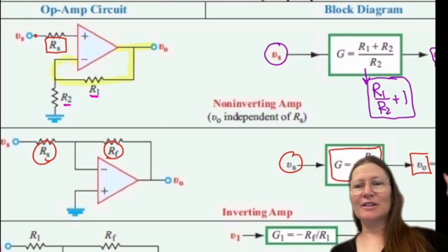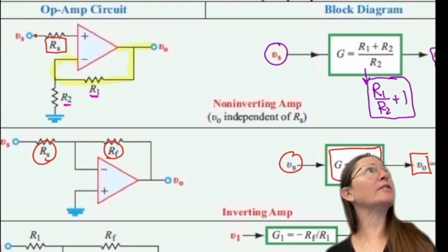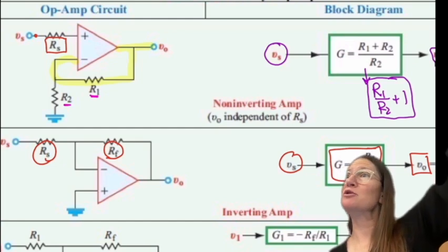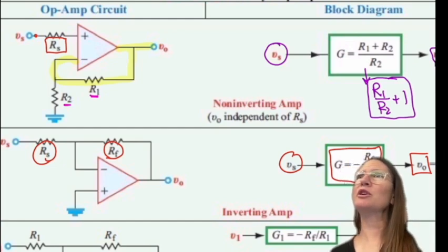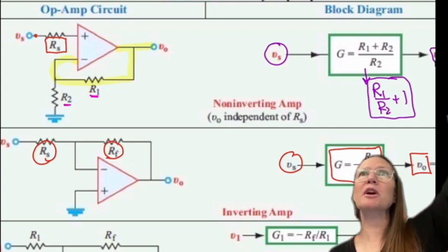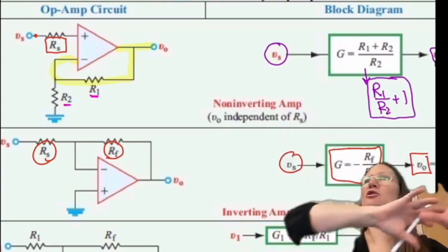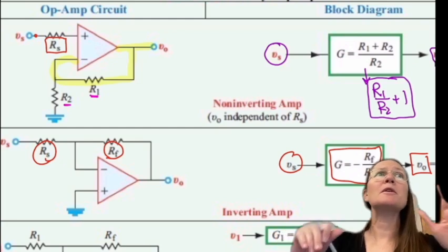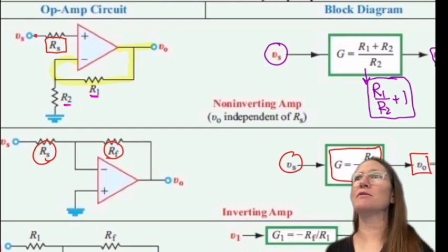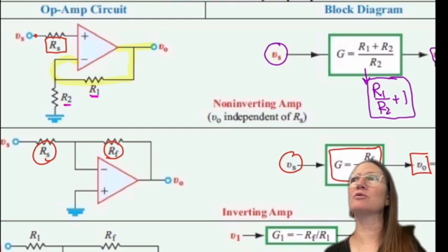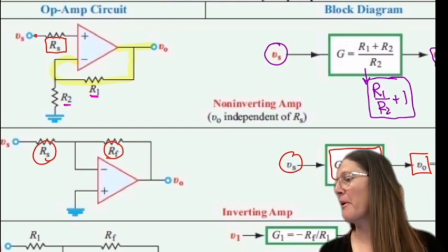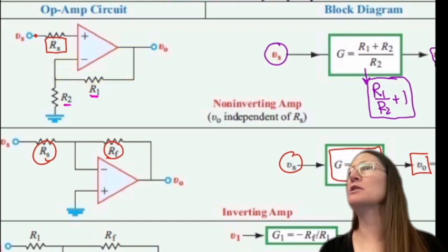Sometimes one of the confusing things is that the power supplies aren't drawn here, but in some circuits on a schematic, you may see the power supplies look like they end up getting back to the input through the power, but that's separate, so that will not be feedback. That's one thing to note and be careful about. All right, other questions or wanting clarification?